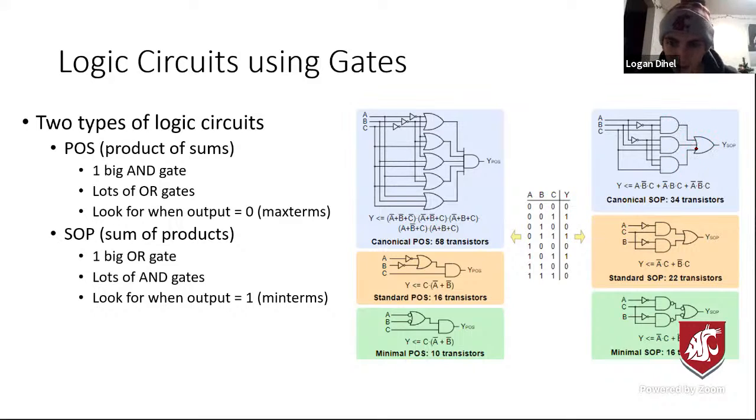The way SOP works is, when you OR values, like let's say we had 0, 0, 1, the output is going to be a 1 because at least one of them is a 1. So we're saying for what combinations we should get a 1 on the output, and we make the AND gates appear as they should. POS is the opposite.